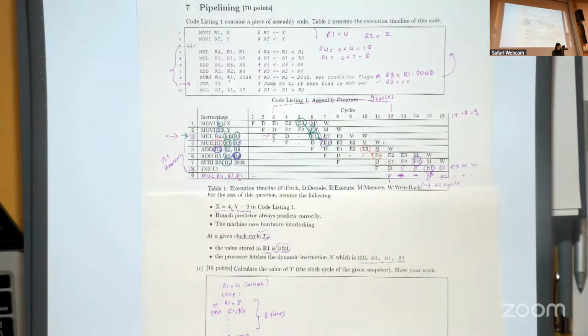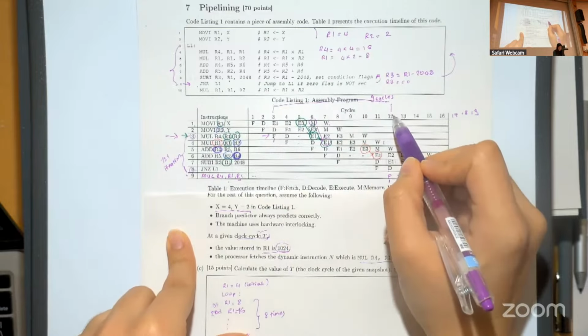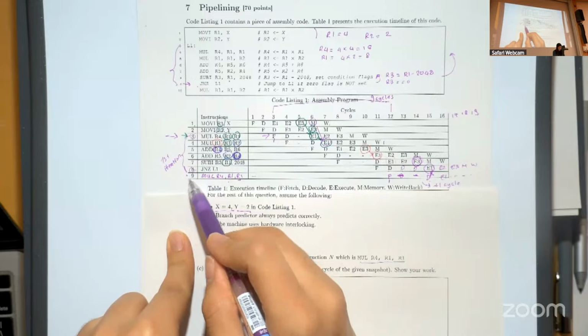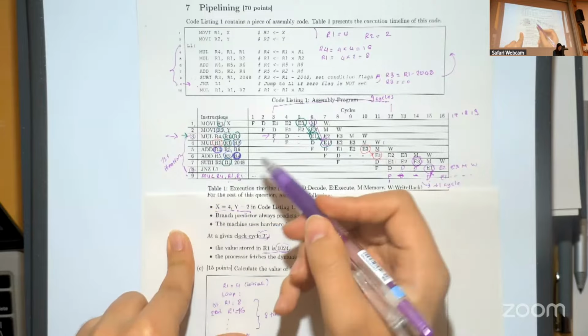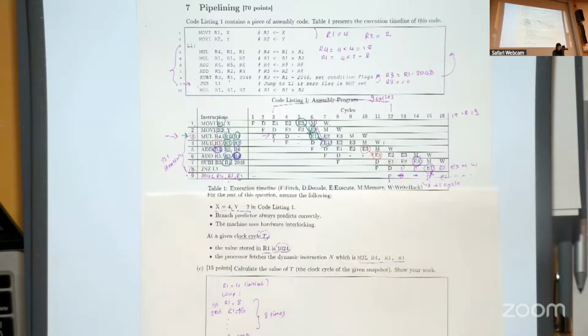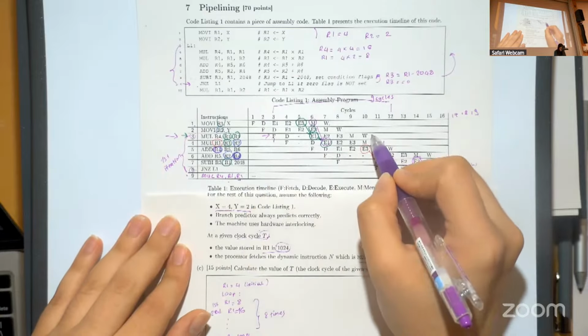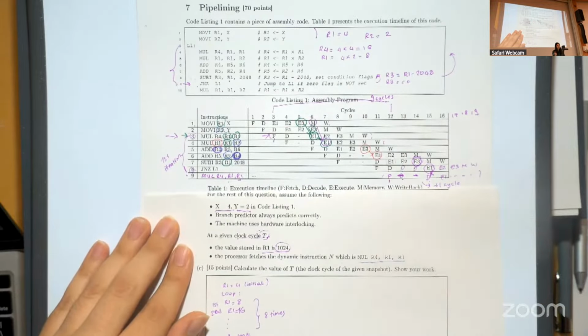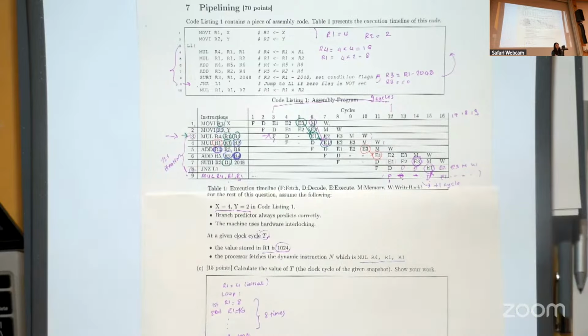Okay, so we first looked at the first iteration and then calculated how many cycles it takes. And then we checked the next iteration by starting at the instruction that is basically our snapshot instruction, to understand if something changes in the second iteration. And at this point, what we see is the execution of the first iteration of this instruction and the next one differs because we have 1 more stall in the decode pipeline stage. So this is why the next iteration will have 1 extra cycle compared to the first iteration. Is that clear?